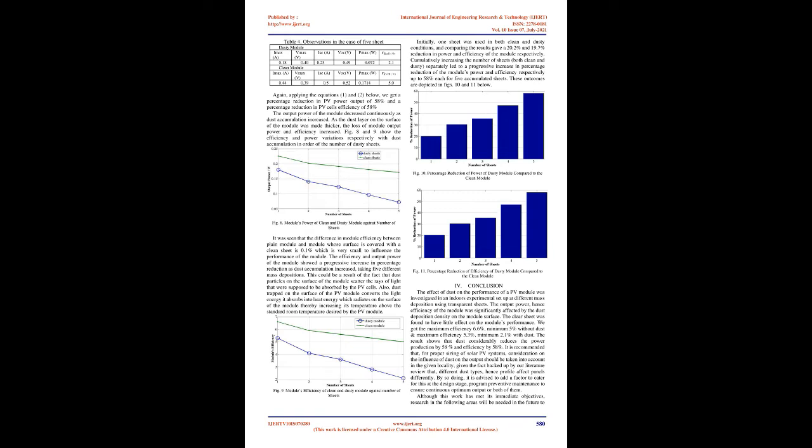With the maximum power, Pmax, as depicted above, the efficiency of the solar module is calculated as η = 0.2294/3.4 × 100 = 6.7%. This is far below the close to 25% efficiency expected from the monocrystalline PV module, reason being that the irradiance is far below the standard test irradiance of 1000 W/m².